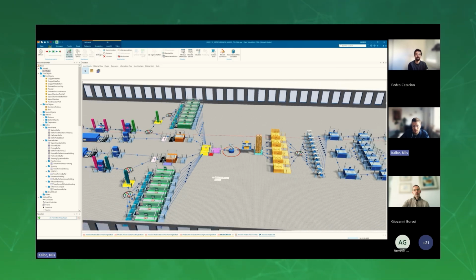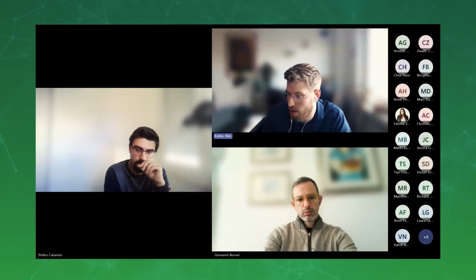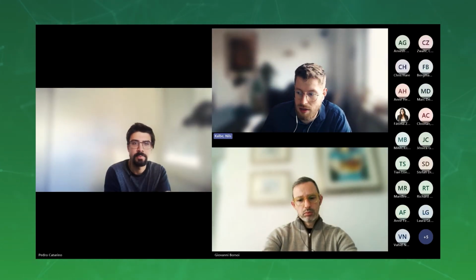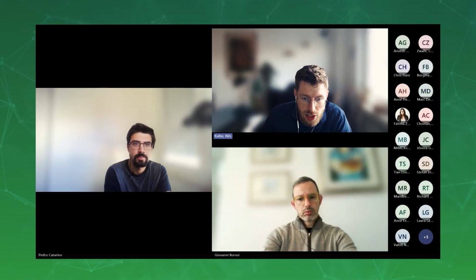So the bottleneck switched from the syntax process to the diffusion bonding, and so we need to find an optimized parameter setting where the system is quite well balanced. Now you can see all buffers are running full, and that has a bad influence on other KPIs. So that's from now. I get back to the presentation again.